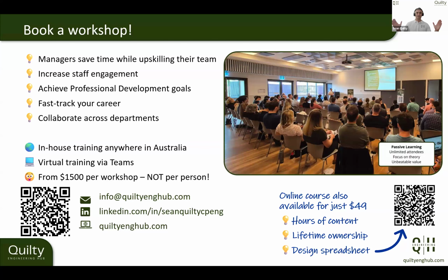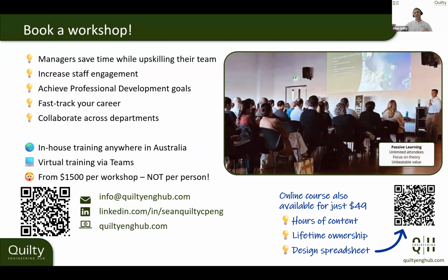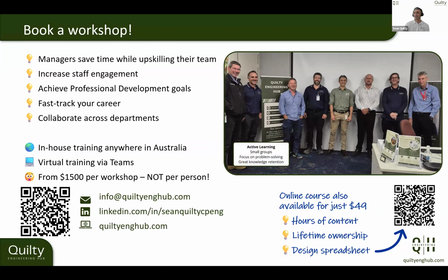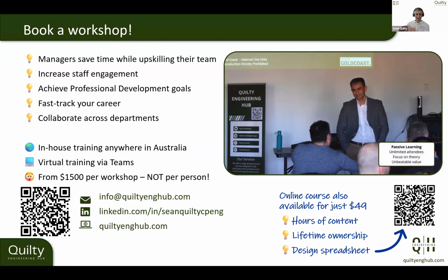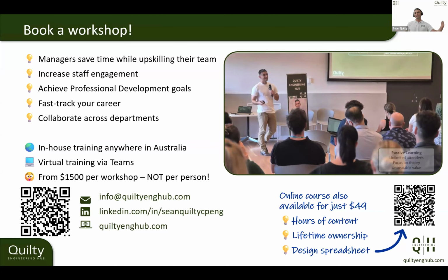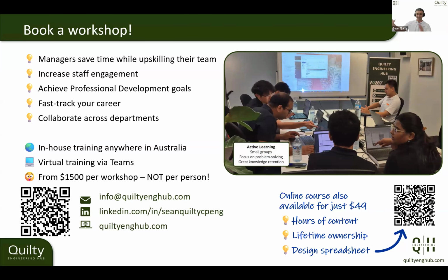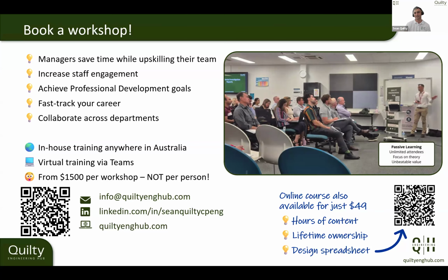And so you've got this spectrum of what might happen, and then you would analyze the risk. Are we happy to accept the risk at the low end and then at the high end? So that's probably what I would incorporate as well. Just how does climate change affect your design? That might mean if there's more intense rainfall and it ends up with more stormwater flow, then you might need to design your channels now to convey your flows now. But then in 80 years' time, when people are still living there, those channels might have to be built up, maybe progressively increased, or maybe you need some planned land resumption, knowing that your channels are going to be twice as big in 60 or 70 years.